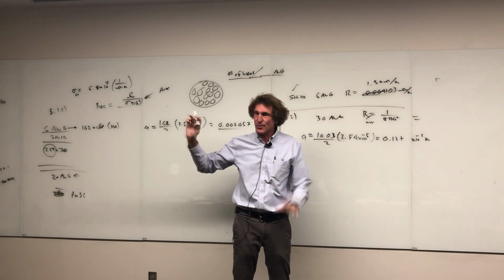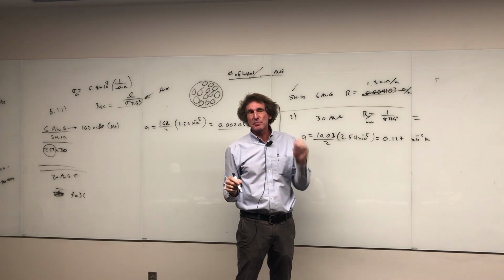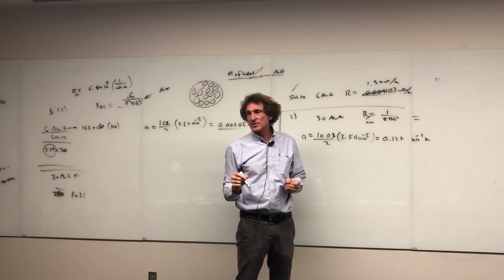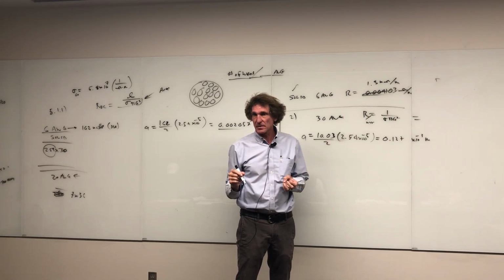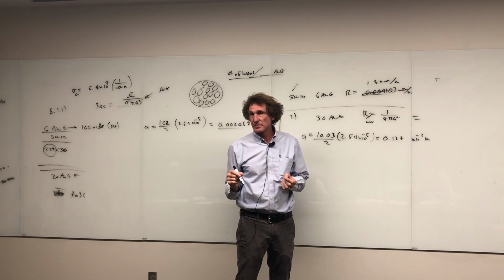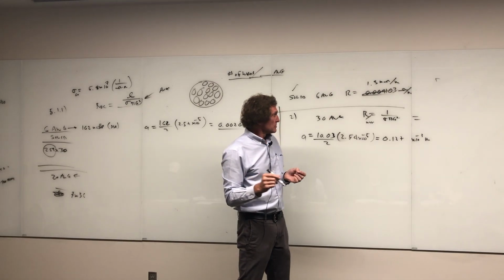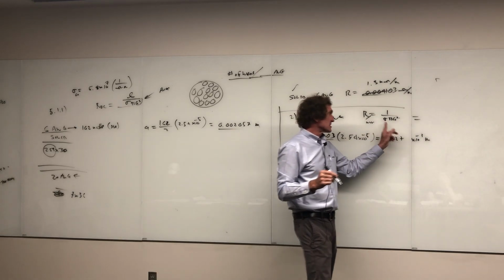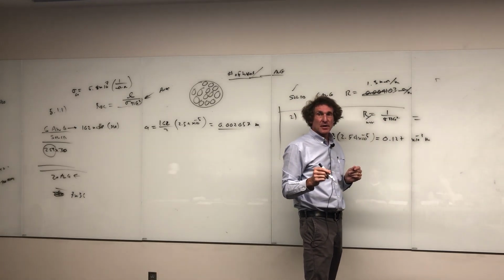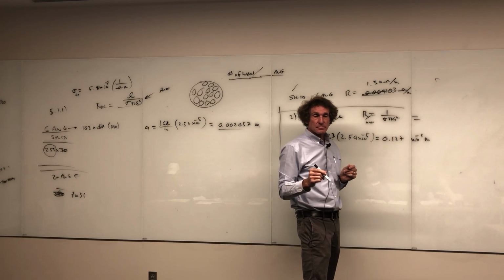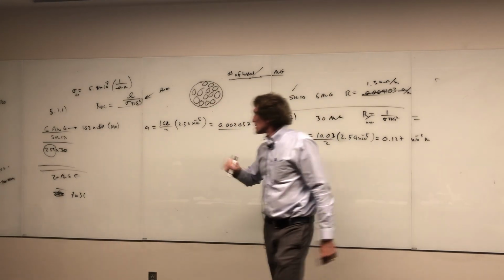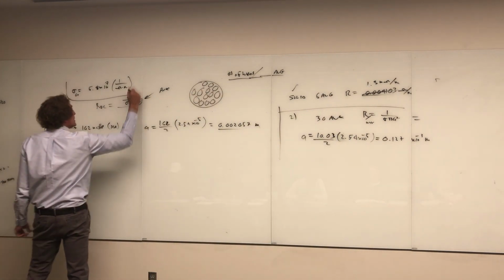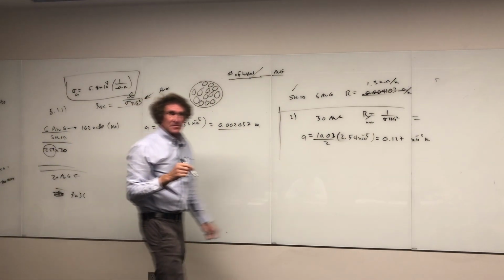Copper. Yeah, they're all copper. Unless it says explicitly it's aluminum or steel, you always assume copper for wire. It's used universally, by the way, not just in this country. I just need this number here. 1 over sigma pi a squared. What's copper? 5.8 times 10 to the 7th. It's right up there. Here, this is the conductivity of copper. You're going to get familiar with this if you're electrical engineers. Electrical and computer. What?